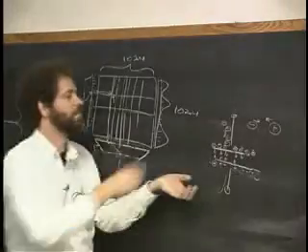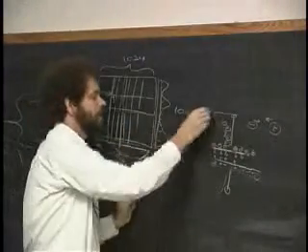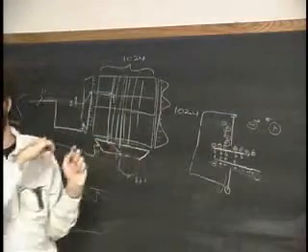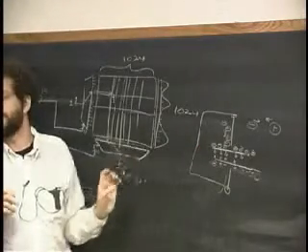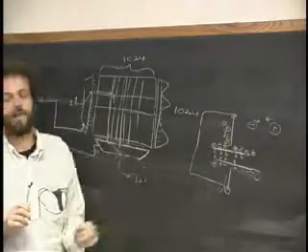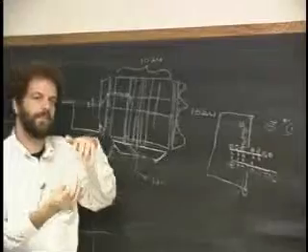And then I can come back and measure the voltage again, or I can suck all the charge out of it by connecting the two ends, or maybe dumping the charge into some other circuit, which is that sense amplifier, and seeing whether or not there was charge. Or I could polarize it the other way, put the positives here and the negatives here. But anyway, that's how it basically works. They're trying to get to each other over the plates.